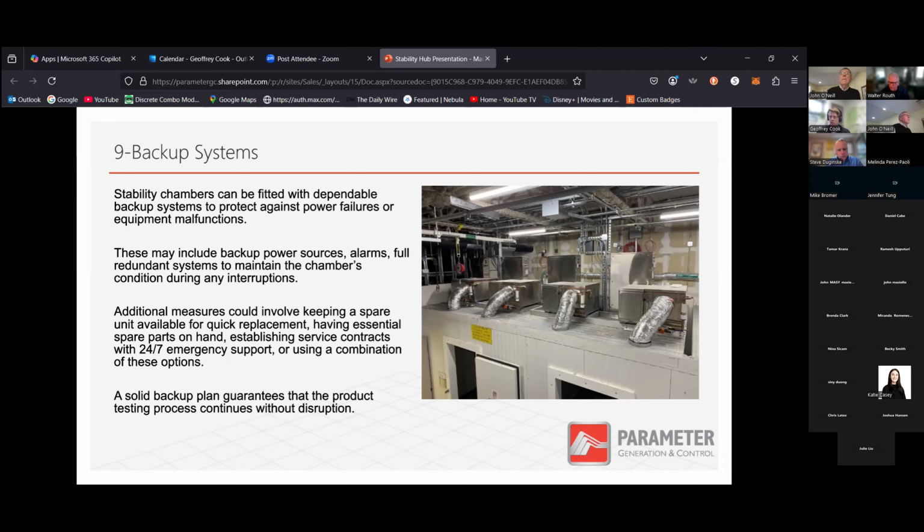If they are automated through your BMS, do you determine a time frequency of change? If it's a freezer, you might not have a time frequency. You might base it on the need to defrost that coil. If you do have those valves and dampers, whether they are manual or automated, do you have the knowledge that you need to switch those systems over when they need to? Does your vendor provide comprehensive operations manuals so that you can read that and switch your unit over in the middle of the night during an alarm condition?